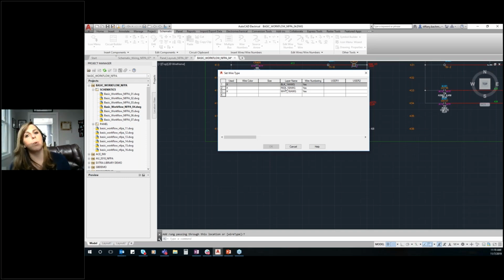But other things that you would put in there would be all of the layers that you want, because wires are layers. These are the only layers we really talk about in AutoCAD Electrical, because the rest of them are already done automatically, but depending on what you place into your drawing, it moves them to the associated layers. AutoCAD Mechanical does this as well. So yet again, something you don't have to think about. You don't have to do that like we do in vanilla AutoCAD, where you're moving objects from layer to layer, changing the current layer, all of that. You don't have to do that.